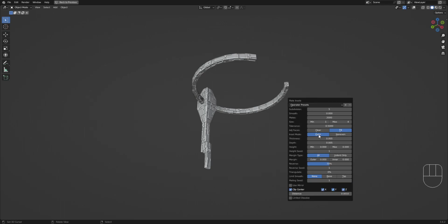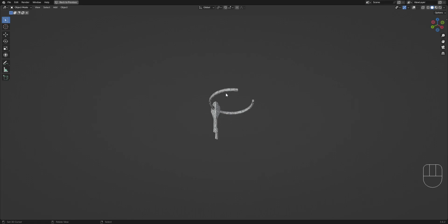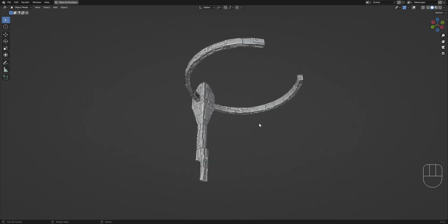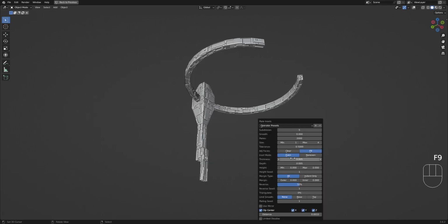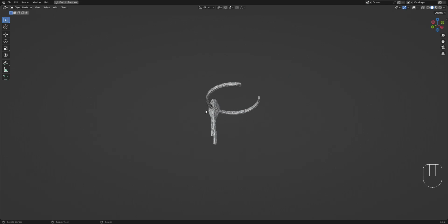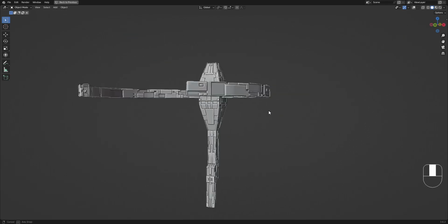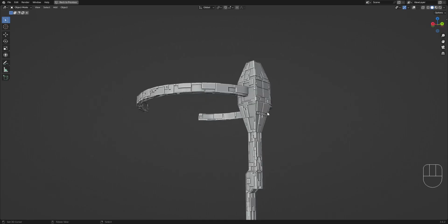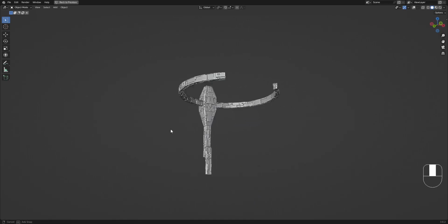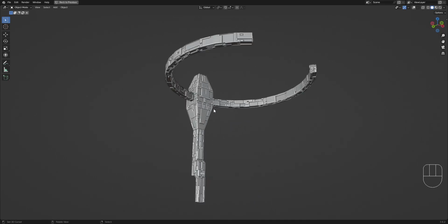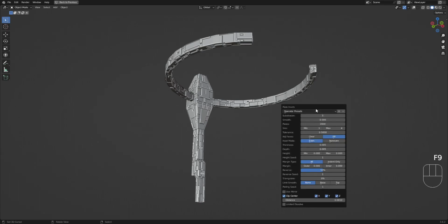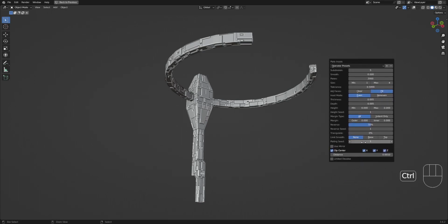If it's too small and you can't really read the details too much at the distance that you're planning to render it, then just go ahead and use less subdivision and bigger faces if you want to make the details more macro at that specific distance. So actually, this could work for us now. It's good. You can of course random seed the result using this plating seed right here.